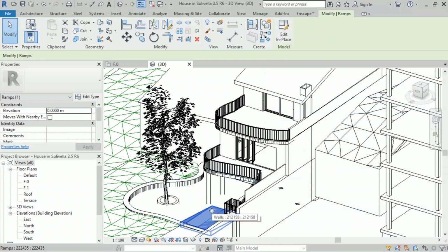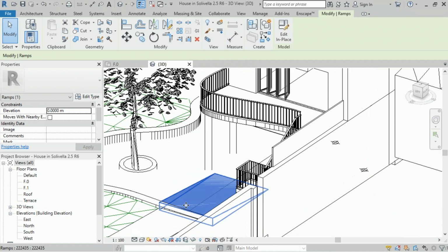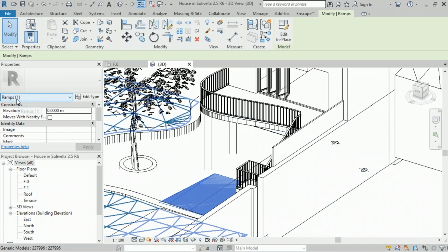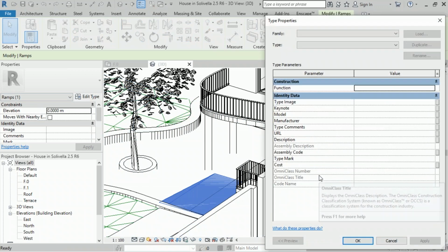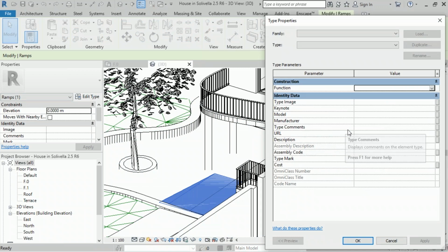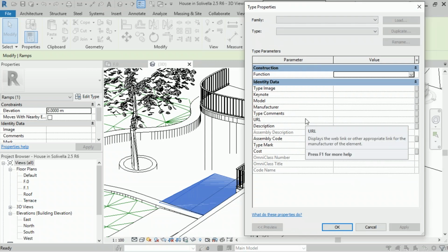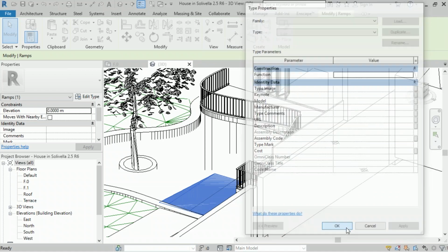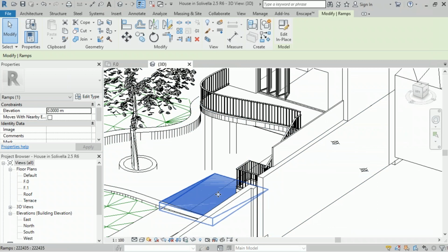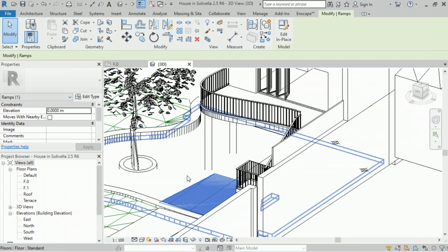But let's take a look at this ramp. Actually it was a polysurface in Rhino, but as you can see, Revit recognizes it as a ramp. If we go to the edit type, we can see there is the unit cost that is missing here. This is something that should be revised, because the custom data on objects should be recognized here, which didn't work in this particular object.